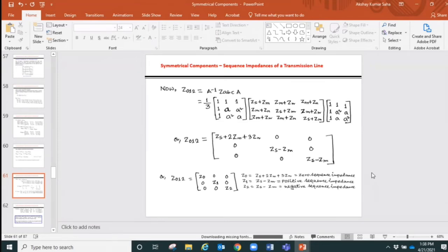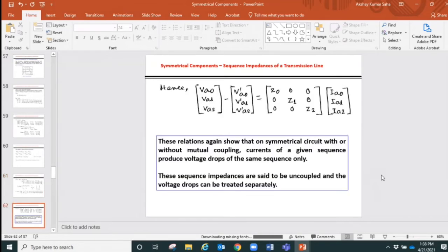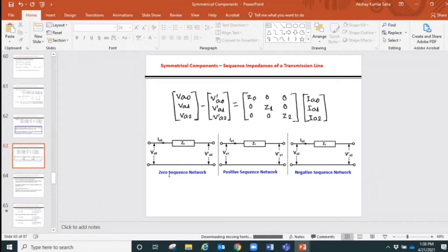And if the mutual impedances are not there, then the 0 sequence value will get reduced. And if we have no impedance on the neutral, then we might find that the positive, negative and 0 sequence impedances become equal to each other, giving one value for all three of them. It's that same condition that we considered earlier. So either we get two different impedances, or we might get one equal impedance for each of those three component impedances. So again, we draw the diagrams coming here.